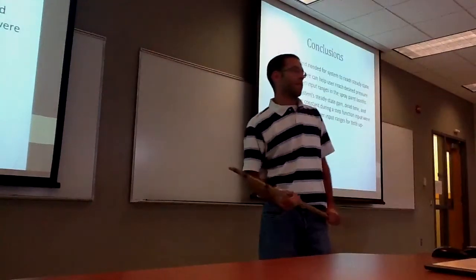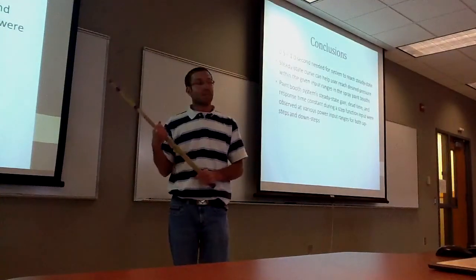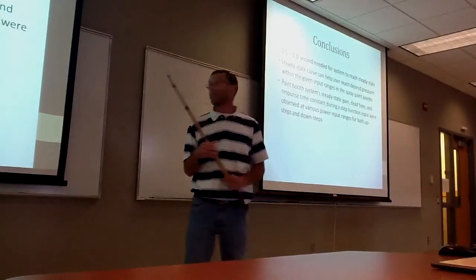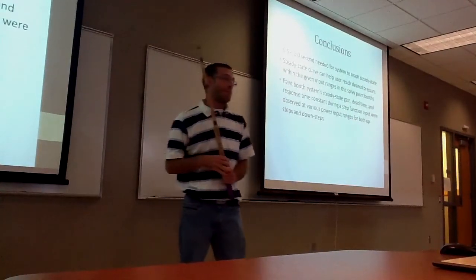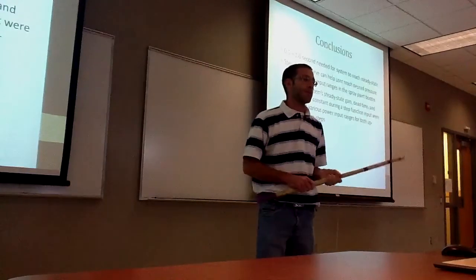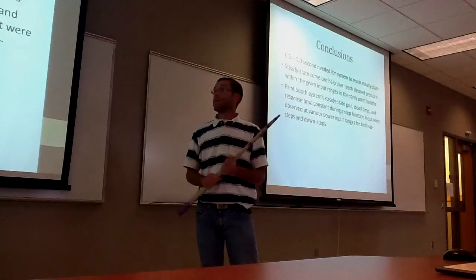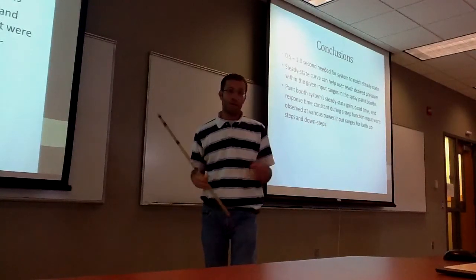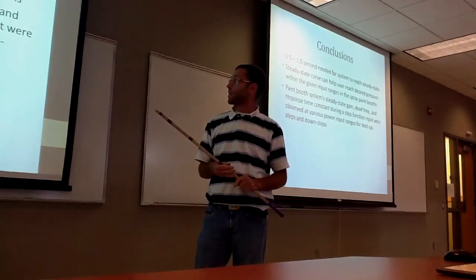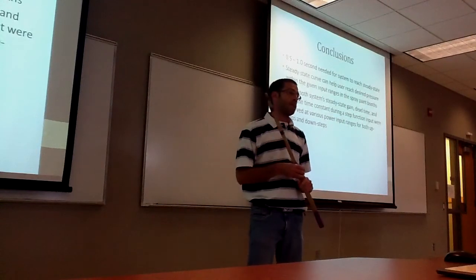In conclusion, we figured out that it takes about half a second to a second for the system to reach steady state once it's turned on. Steady state curve can help the user reach desired pressure within the given input ranges. But more work would have to be done in order to figure it out across the whole scope of it, which would be 0 to 100%. And the paint booth system's steady state gain, dead time, and response time